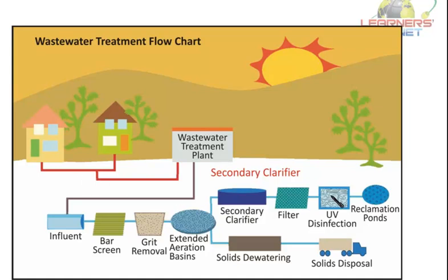So basically in the tertiary process, disinfection typically with chlorine can be the final step before discharge of the effluent. However, some environmental authorities are concerned that chlorine residuals in the effluent can be a problem in their own right, and that is why they have moved away from this process.